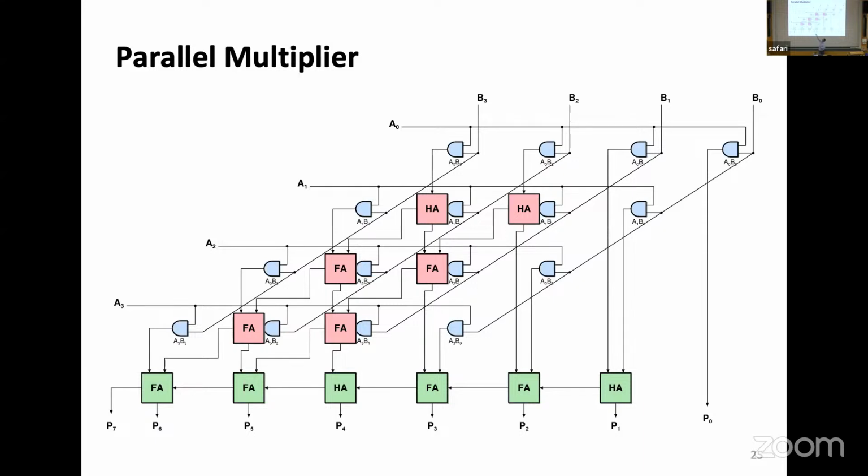Okay, let's start. I have A here, A0, A1, A2, A3. I have B, the other number that comes in at the top, and I'm generating the partial products by the blue AND gate. So you can see the B0 times A0 is right there at the top. And then I'm creating A0, B1 and A1, B0. Okay. And then the red guys are my carry save adders. And the last portion here is the one that does the carry propagation at the very end.